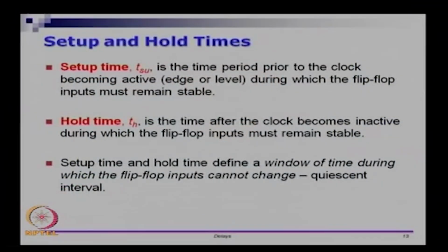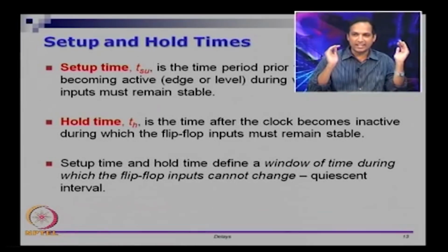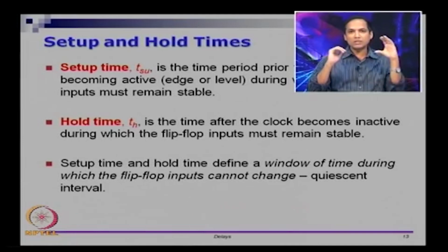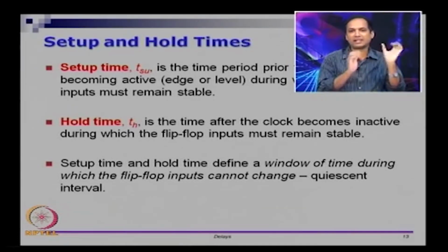Setup time, usually referred to as T subscript SU, is the time period prior to the clock. Remember, we are talking about sequential elements here, so there is always the notion of clock. So TSU is the time period before the clock becoming active, during which the inputs to a flip flop must remain stable. We are talking about a flip flop, it has a clock and it has a data input, and you want to keep the data input stable for some amount of time before the clock comes in, and this is called the setup time.